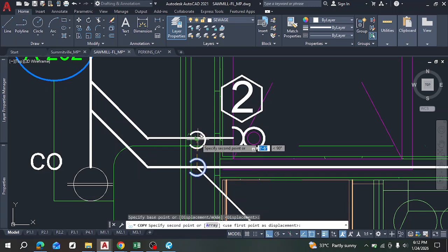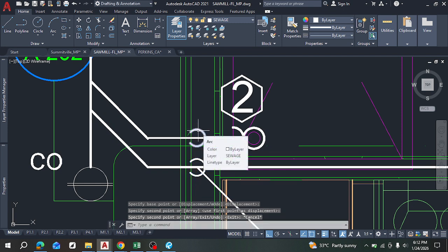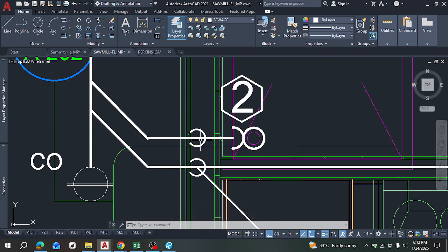Now you see that this alone has made me add another vertical pipe for venting, and has made me add extra pipe. So these are the questions you ask yourself: is this design worth it? Is it economic? Because economic means using the least amount of items, but it also needs to be optimal so that you don't save materials at the cost of efficiency, right? So you ask yourself if it is worth it for the design to be like this, right? So there'll be two pipes traveling beside each other, right? So that's why I selected that former method. Control Z.